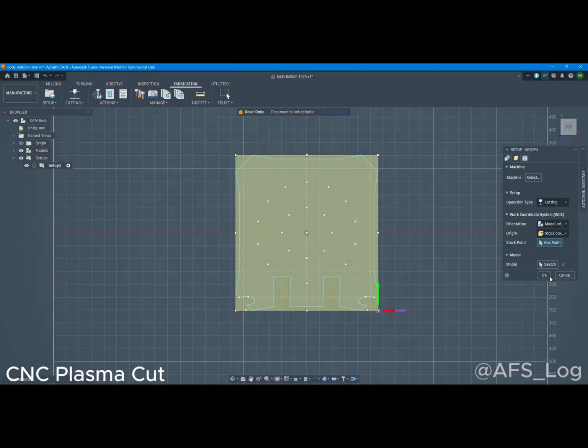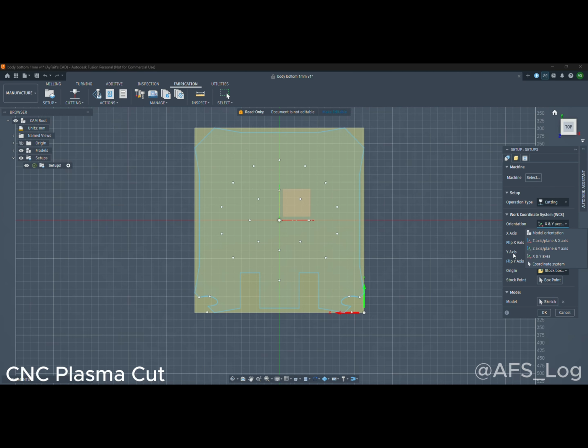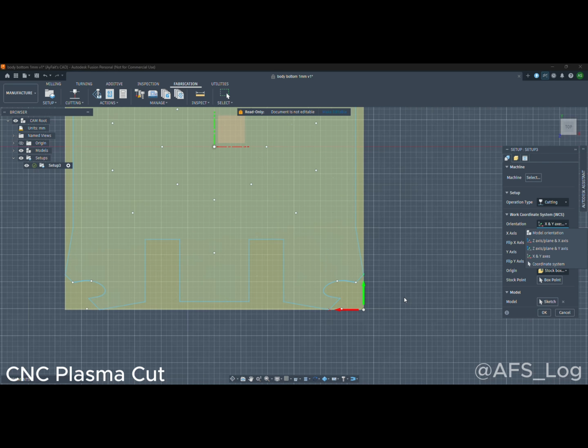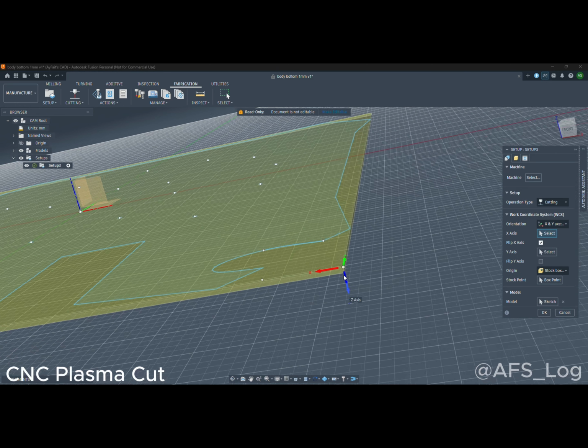So I've selected, you can select anywhere, and then from there, I don't want to go into the details of this one much, but you can also change the direction of your Cartesian coordinates, which you see now we have the x negative direction and the z, but this is not advisable. Now, if you notice, the orientation has changed. It's saying x and y axis. So the z has turned upside down. Now this is top, right? Initially the z was pointing upward out of our profile. But if you look at what I'm going to show you right now, you'll notice the z is now pointing downward. It's pointing in the opposite direction of our profile.